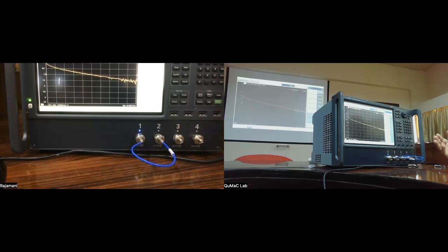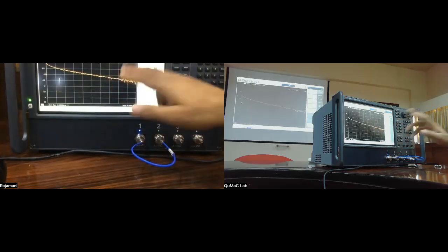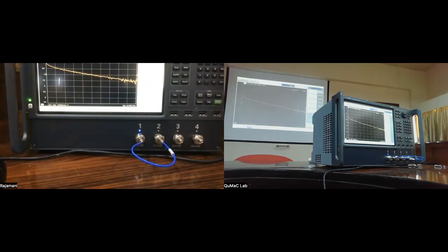And usually, with factory setting, it comes with a default thing, but that instrument is quite old and has not been calibrated in quite a lot of time. So we're talking about very small mismatches. That's fine. This doesn't mean that there's something unphysical going on, because otherwise a passive circuit showing S21 different than S12 means there's something seriously wrong with that device or with the instrument.